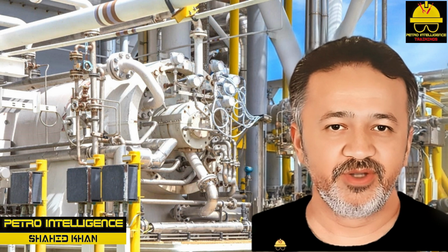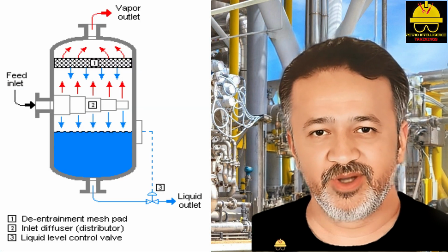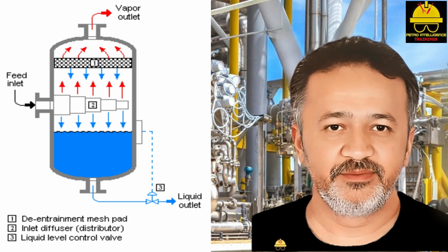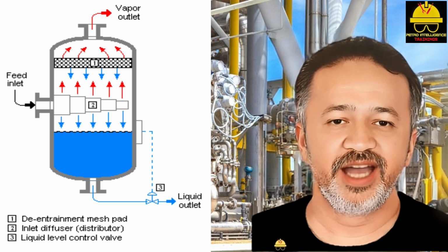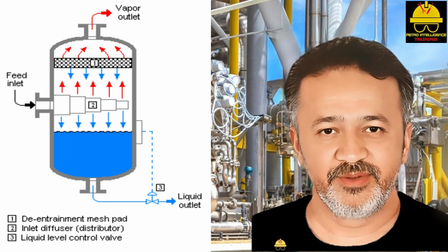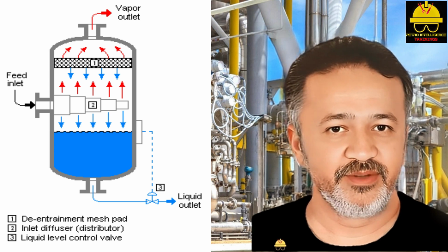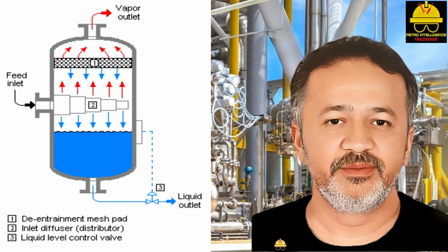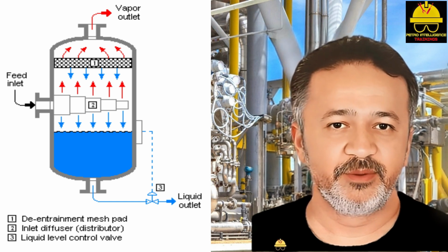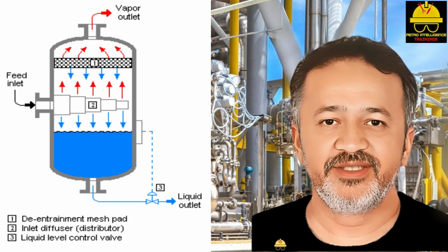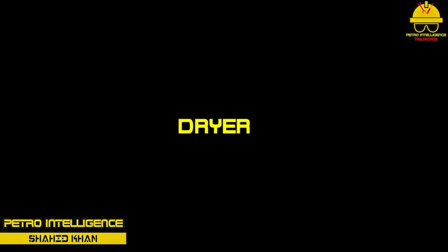Demister. A demister is a device designed to remove liquid droplets from gas. Demisters function along the same lines as a cyclone. As gas enters the top of the demister, it is swirled around the outer perimeter of the canister. Because liquid is heavier than air, centrifugal force brings it into contact with the outer wall. The heavier component falls to the bottom of the demister and is removed. Clean gas escapes out the discharge line on the top of the demister. Many positive displacement compressors would be damaged if wet gases were introduced.